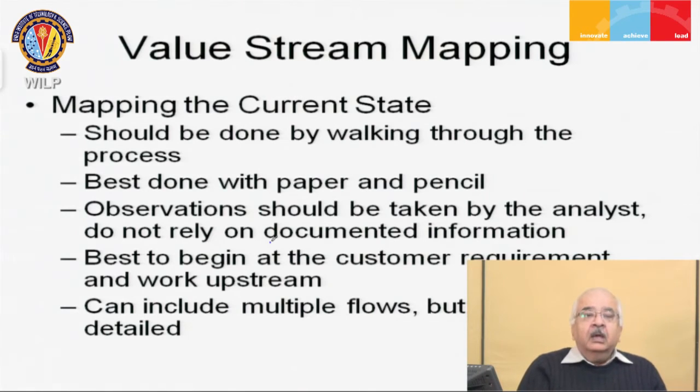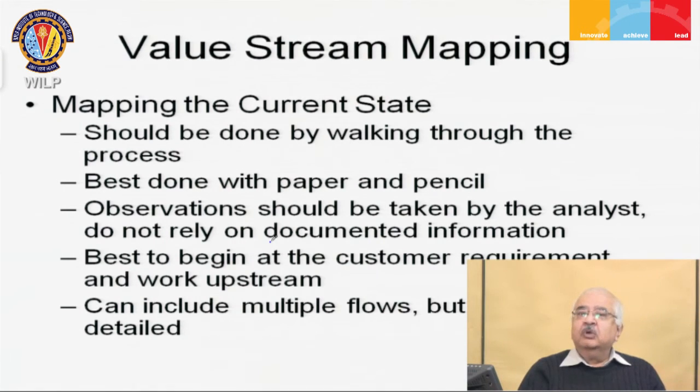Now, when you are mapping the current state, what is it that you need to do? A few pointers. Number one, you cannot draw a current state map sitting in an office. You cannot map a particular process without actually going to the shop floor.